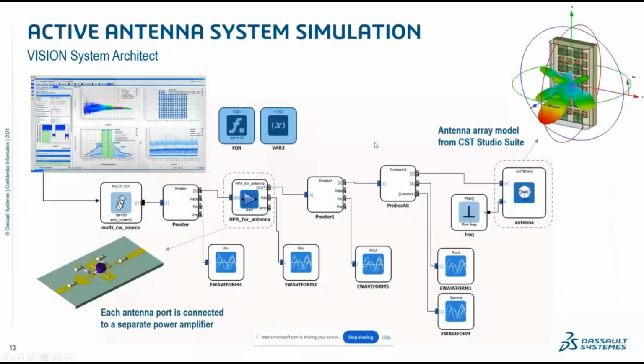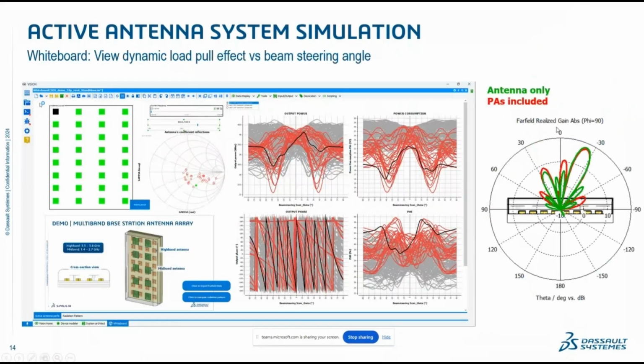Last year, again, we expanded the portfolio, enabling you to do the system simulation, not only the 3D electromagnetic simulation of the antenna or antenna arrays, but now you can also include the power amplifier, for instance, to do a system simulation of the communication, entire communication model. With that, you can see the effect of power amplifier, like intermodulation or unwanted operation scenario with the power amplifier on the performance of the antenna.